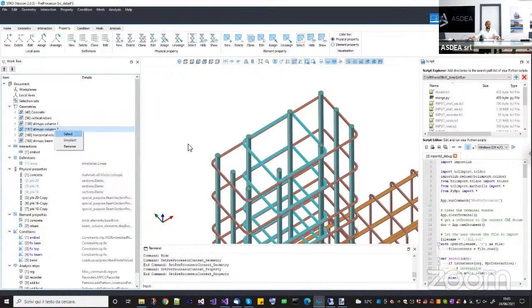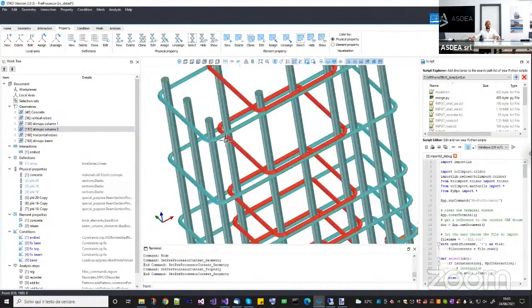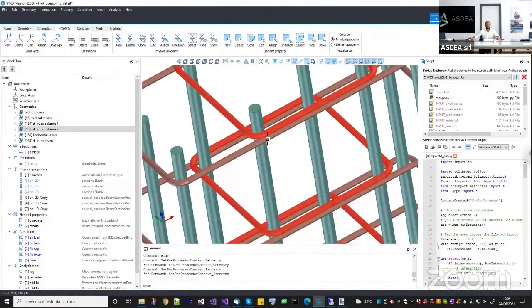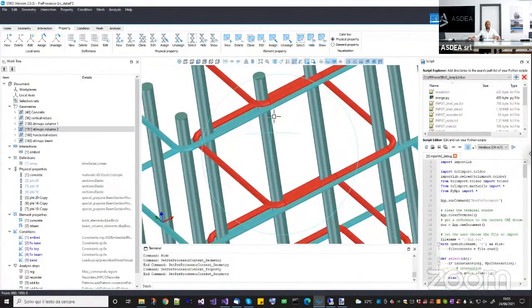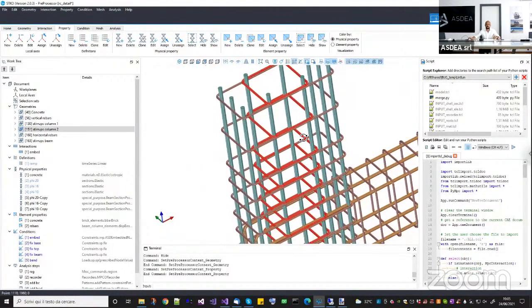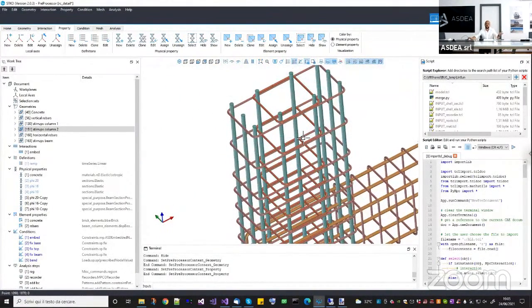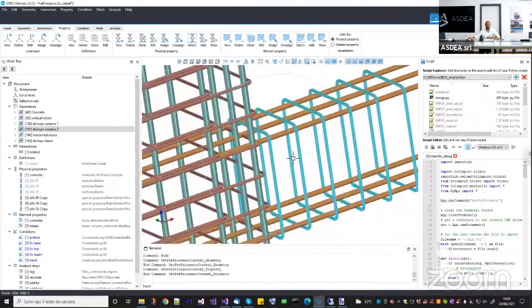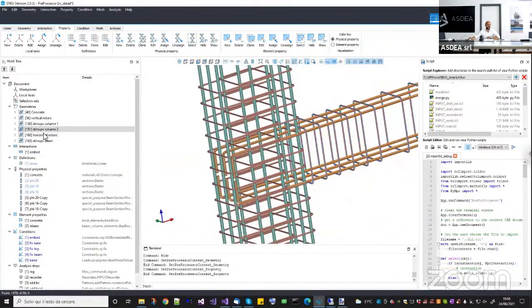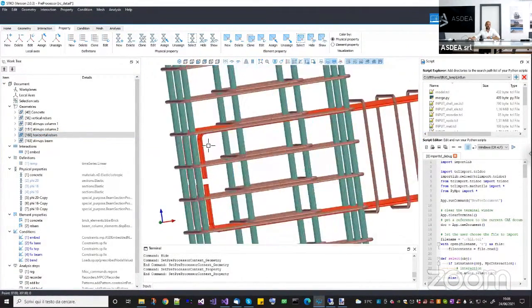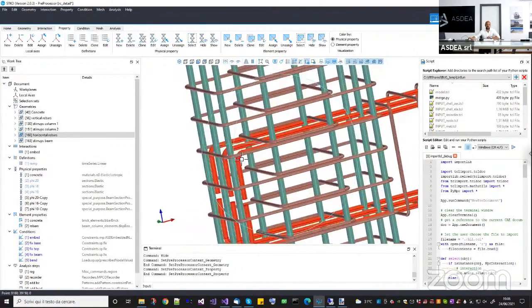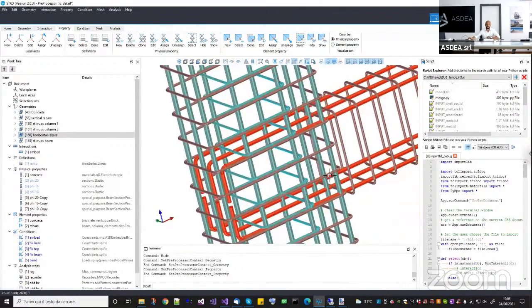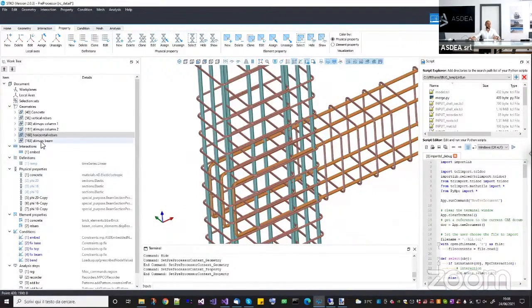Select. And as you can see, you're free to create stirrups with chamfers. They can be overlapping or they can have a real offset. It's not important because you are not going to do any cut in the solid geometry. And then the same thing for the beam. Here I have my horizontal rebars. You can create also the anchorage here. So you can go into whatever kind of detail you want, okay? And also the stirrups for the beam.